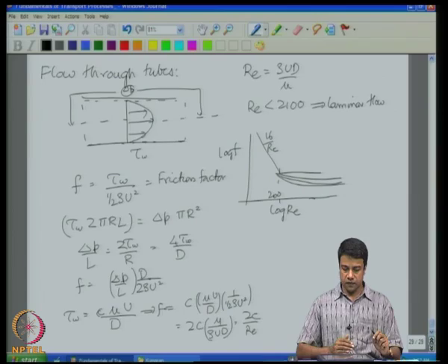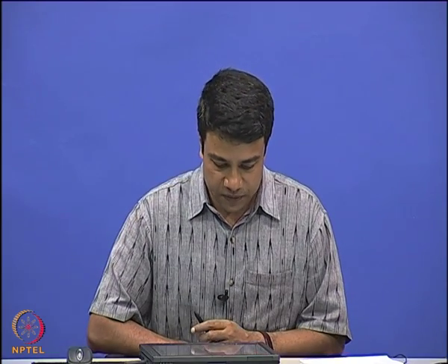In the case of momentum transfer, flow through tubes and flow past objects, it is more traditional to define these dimensionless groups in terms of the drag coefficient or the friction coefficient. Both of these are momentum transport rates scaled by the kinetic energy per unit volume. In the case of momentum transfer, these dimensionless transport rates are functions only of the Reynolds number, because there is only convection and diffusion.